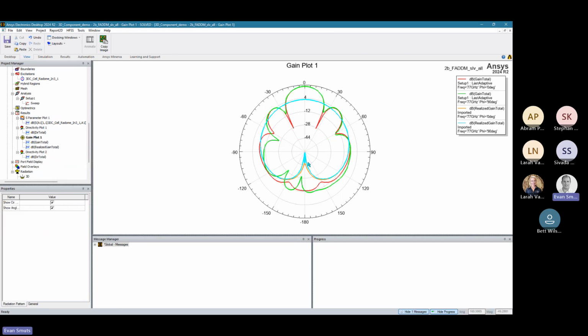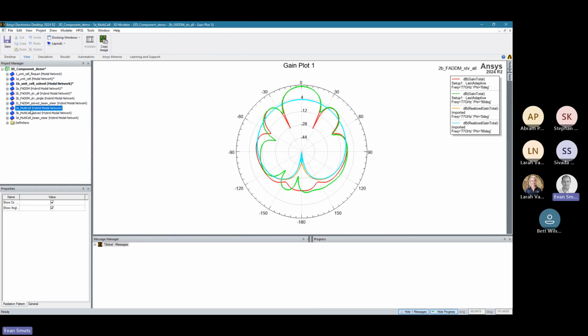So now we can see our radiated pattern from a previous design and how that compares to this current model. So we can see that for this 5x5 array, we are getting better directivity there, and we can see where all the other side lobes and everything are created. Okay, so that is our finite array method.